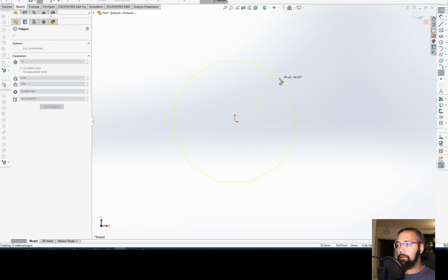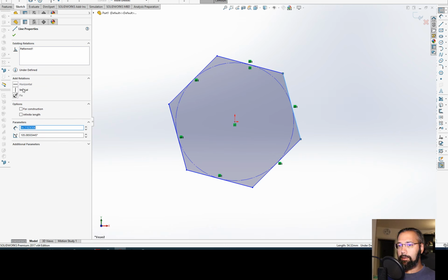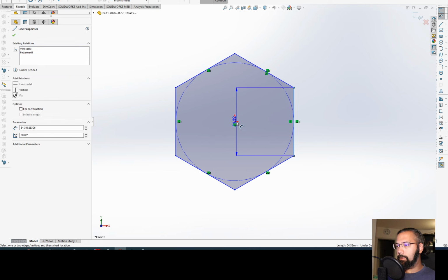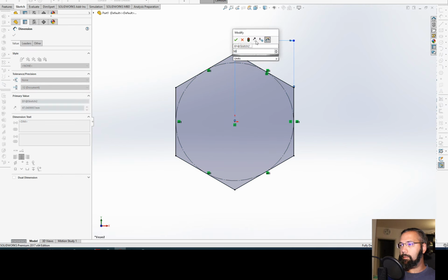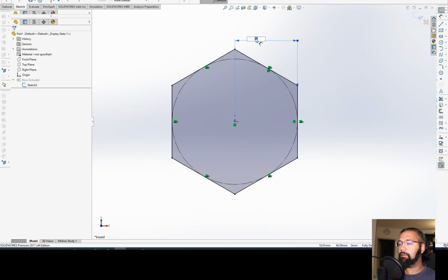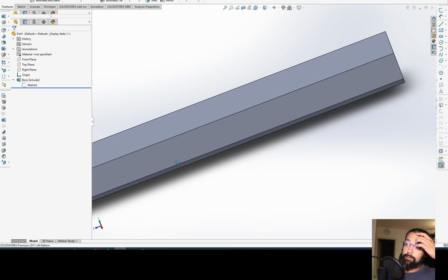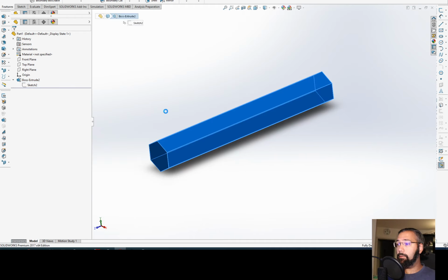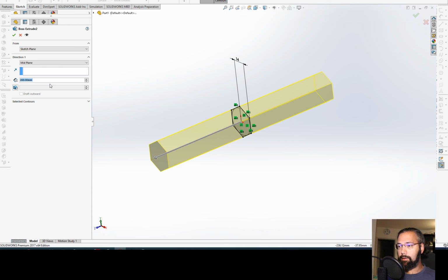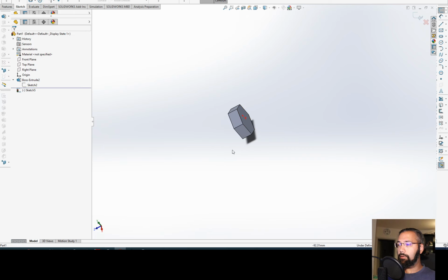If you want a polygon that has 6 sides, so a hexagon, you can tell this line you are now vertical. You can tell it that, let's say, it is 14 millimeters away from that. And then you go back. You tell it, you are 10 millimeters thick. Then you take and extrude.